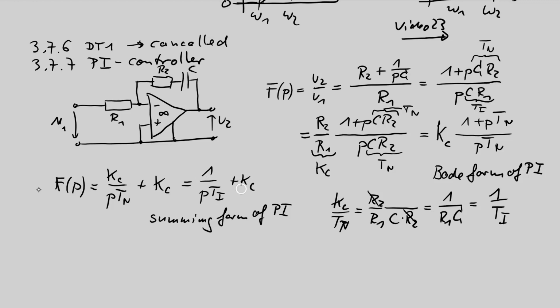Some people prefer this, other people prefer that. With this you can draw the Bode plot very well, with this you can calculate the step response very well. So depending on the application, one or the other is more suitable. Okay, let's take some minutes for the step response of a PI.